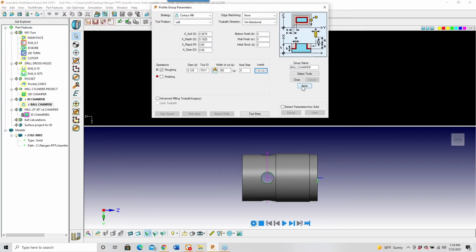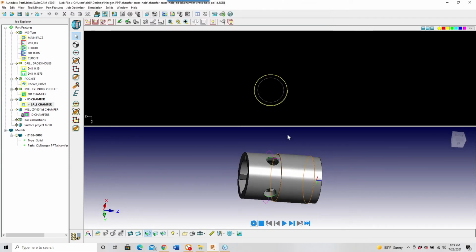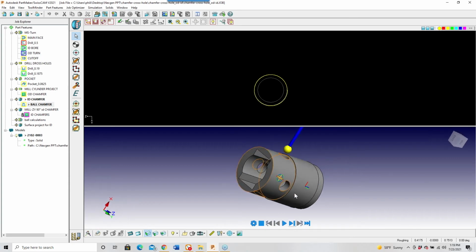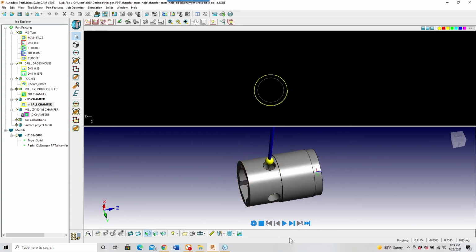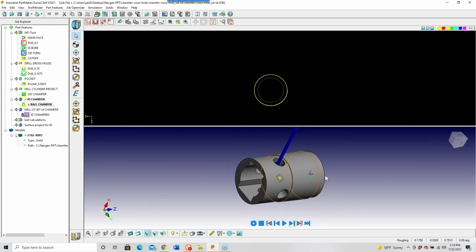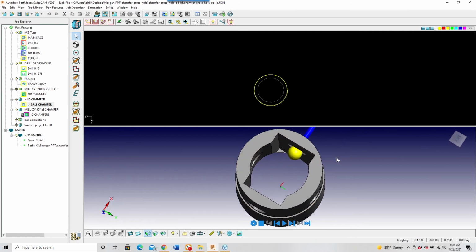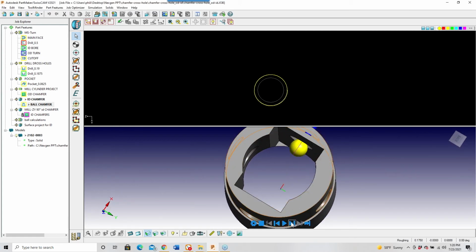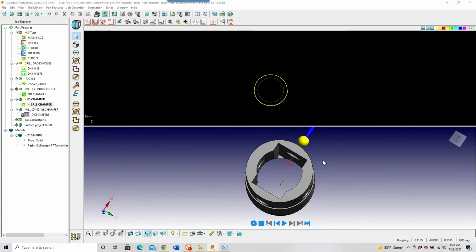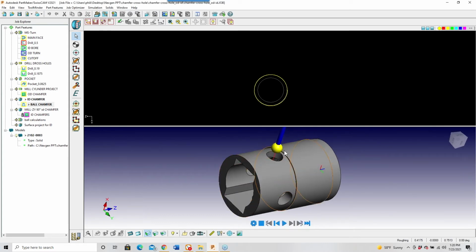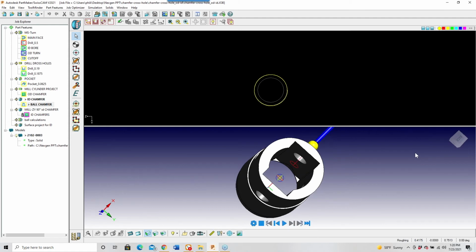So if I've done this correctly, the tool should find the center of the hole, move down the distance as required, step over to the geometry that I chained, and cut the inner edge and back out. Again, back to the center of the hole and retract.